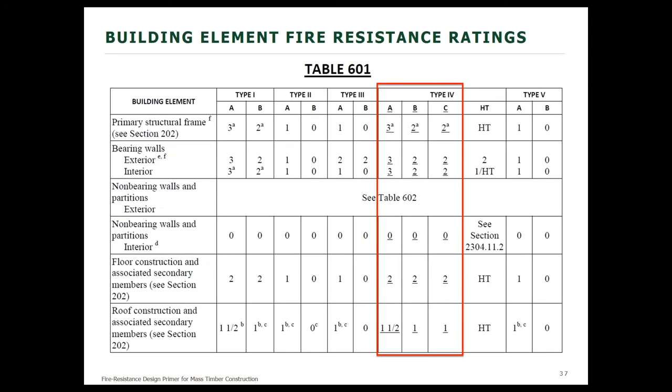So in reality, where it's calling out for 1 hour, you would need to actually go through that calculation, using our Chapter 16, to establish that 1-hour fire resistive rating for the glulam. Again, one thing that I don't think we touched on in here is, when you're dealing with the glulam, the fact that you have to add that one extra layer out in those tension laminations.